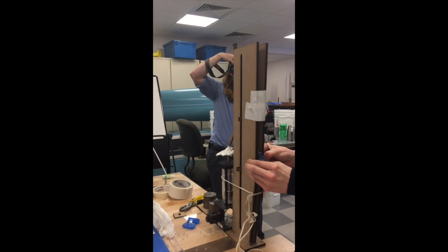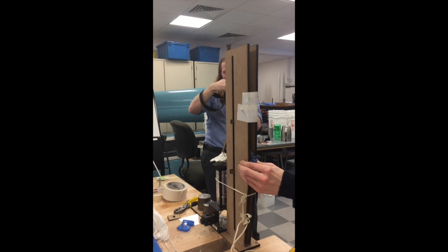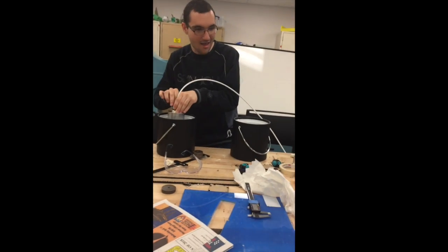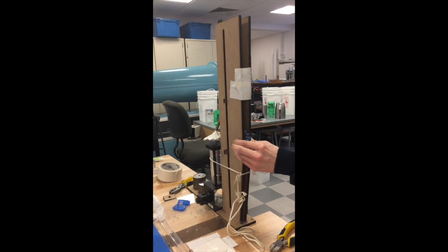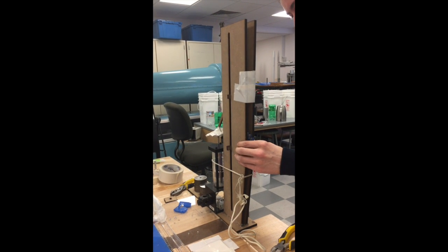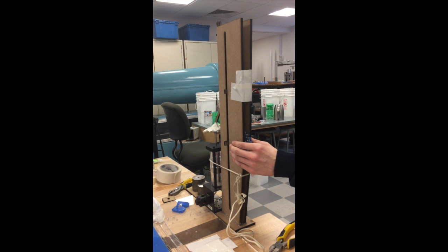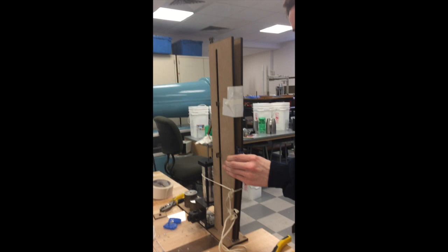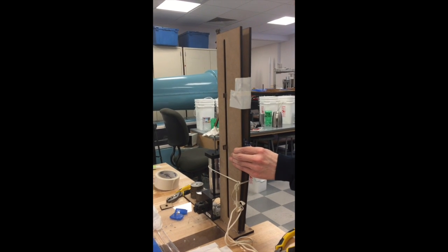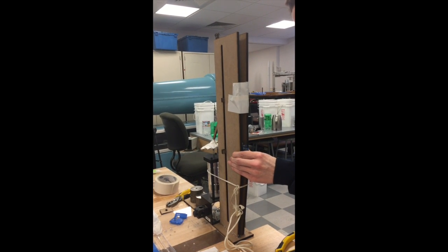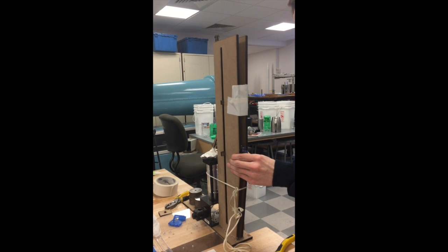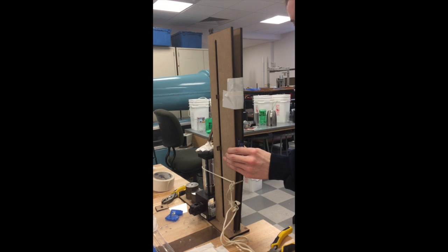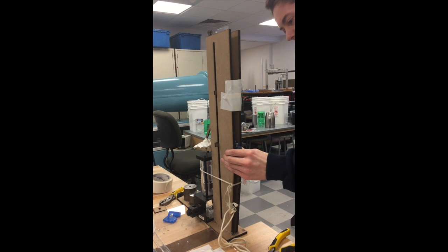There were many reasons for deviations. For instance, while we did not calculate to include friction, the actual testing mechanism had noticeable friction in the pinion and rack mechanism, as well as with the rack and the walls of our mechanism. Additionally, the distance between the teeth of the rack were not ideal for our system. Previously, we had not thought to account for the teeth distance being important. However, upon review during lecture, we now understand that we should have calculated for the ideal distance between the teeth in order to ensure that all work from the piston could be gathered in our storage of potential energy mechanism.